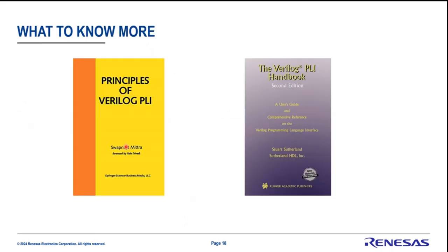So if you want to know more, the only two books on the VPI or the PLI layer and how you do the communications are up on screen. What I would suggest, if you are going down this route, is first of all sync up with your EDA vendor. It may be they've got some of these routines available for you, or they might want to work with you on building them.